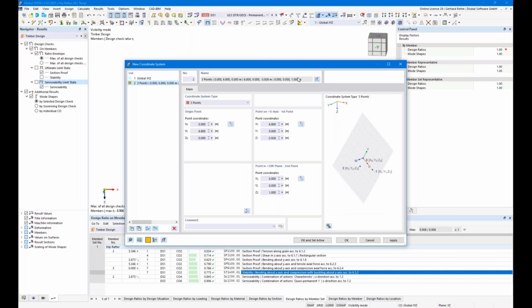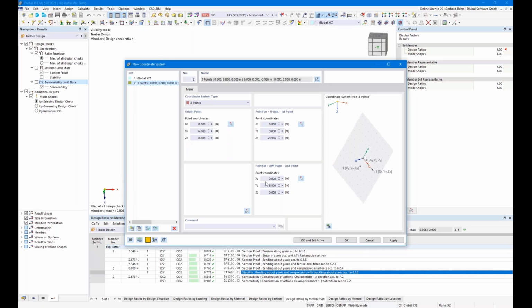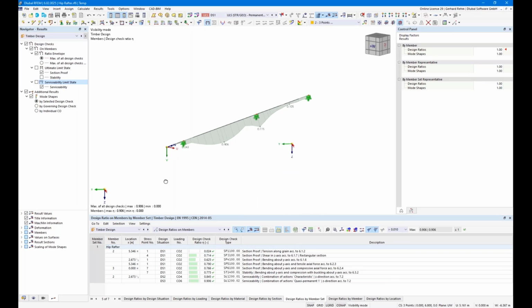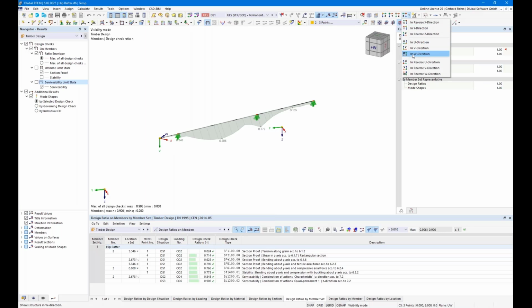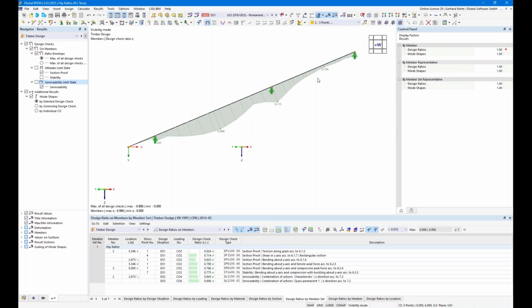The U-axis is defined by this point, and the plane is defined here. We change the coordinates easily, and this one should be at 0 coordinate. Now we have this user-defined coordinate system, and I'm able to check the view directly in W direction. That helps me to get the full length. All right.